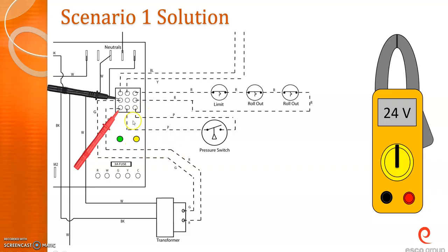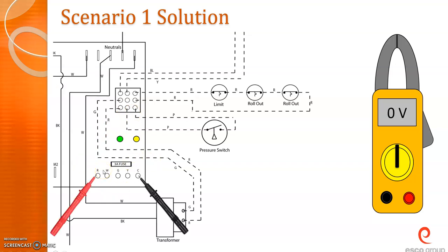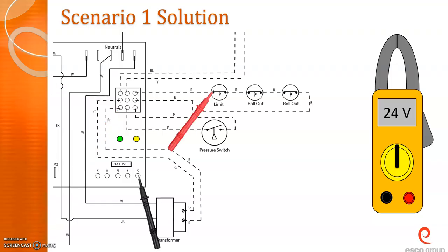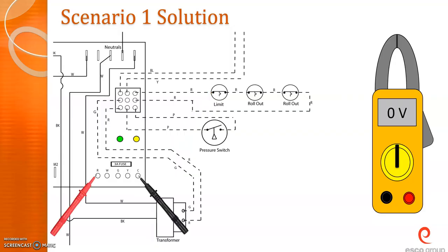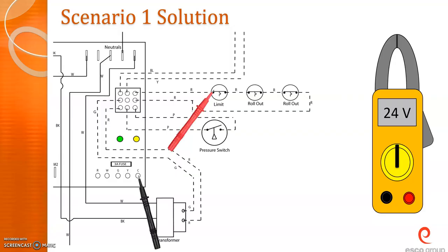But assuming you have your 24 volts to the board, then that board is going to send out red back to the thermostat, and then that white is going to come back on everything else. And so in this scenario, this is giving us the option. It's going to do some checking. I'm assuming we are getting a call for white. It didn't actually check that on here, which I would have checked.